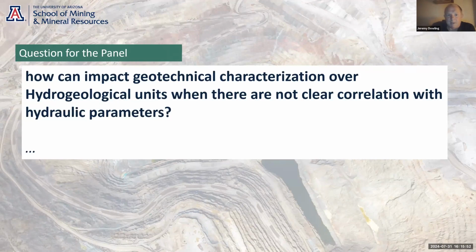So install test holes and piezometers and drains or wells, and make sure there's a good understanding of those higher risk geotechnical domains, so that there's a clear understanding of how the pore pressures can be controlled as it's mined.